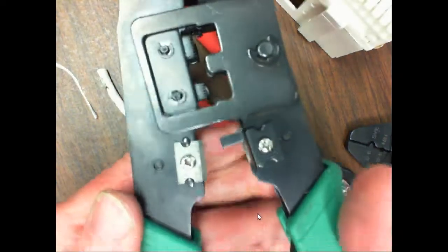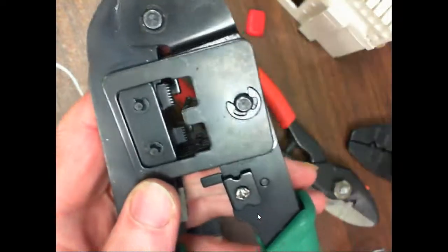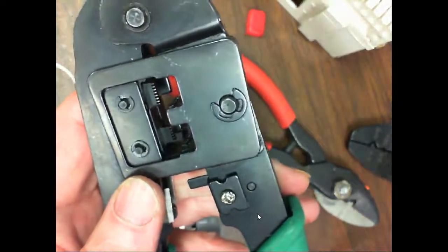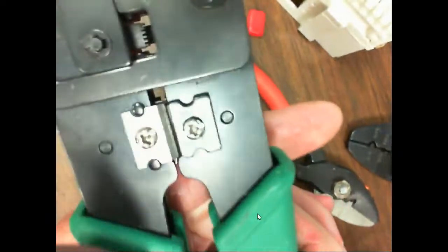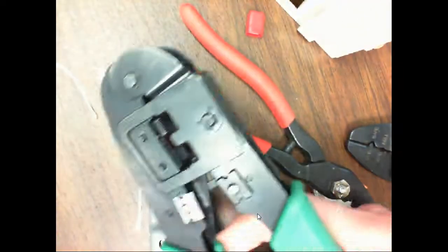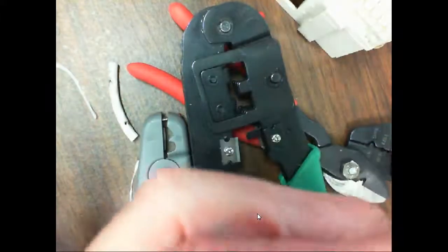So here's the crimp tool. Now these are the blades that are going to insert up there and actually push those conductors up, push those blades up in there. But what's nice, it's got this cutter right here that allows me to come and do what? Cut this off to the length that I want. And I'm not going to measure this out.